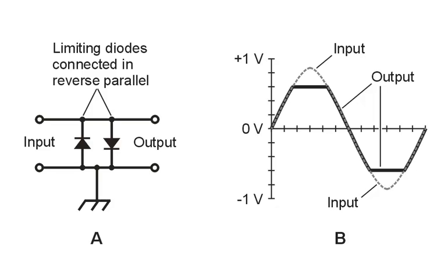Here is an explanation for the answer to final exam question number 30 in Electronics Demystified 2nd edition. If you have the printed book, you'll find it on page 423. In a wireless communications receiver, we can connect a pair of diodes in reverse parallel with variable reverse bias across the audio output terminals to obtain what? Well, the answer is noise limiting.